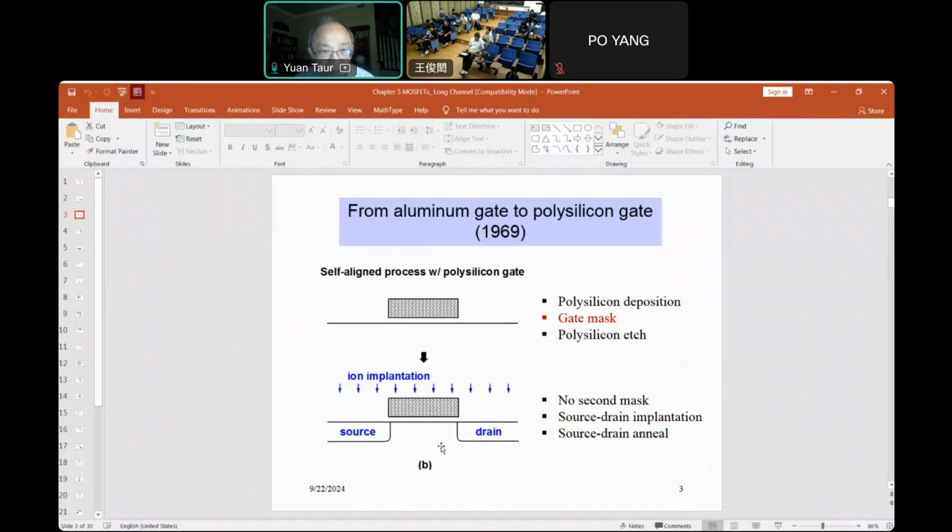In other words, you still go through with a self-aligned process, and then you cover the whole thing, dig out the polysilicon, and refill this part with whatever metal you want to use for the threshold voltage control. In that way, the alignment is similar to the polysilicon gate, but you change the work function, and there's no depletion problem because we replace the polysilicon with metal.